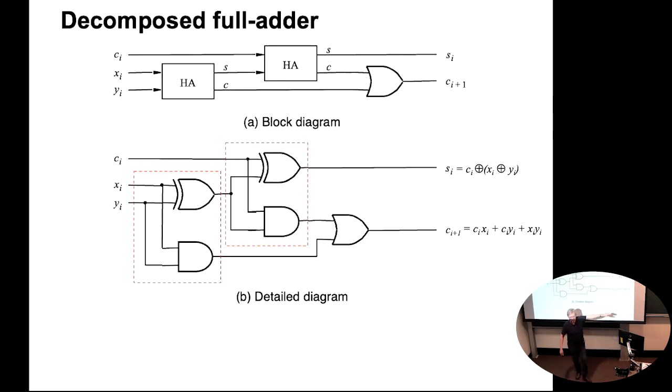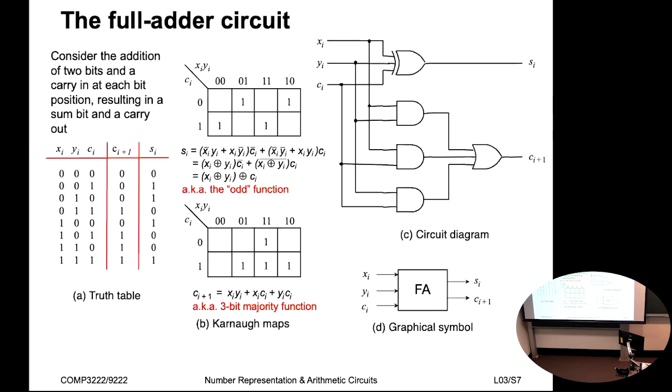You can formally prove that too by playing the same trick as we played with the consensus theorem, simply by combining Xi, Yi with C or C bar. That expands the expression, and that equates to these terms over here.